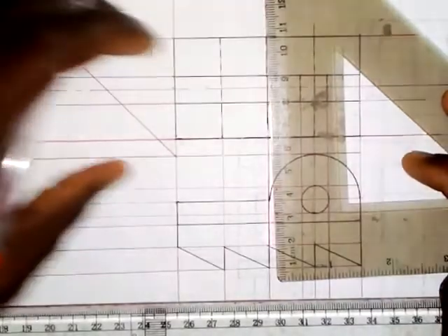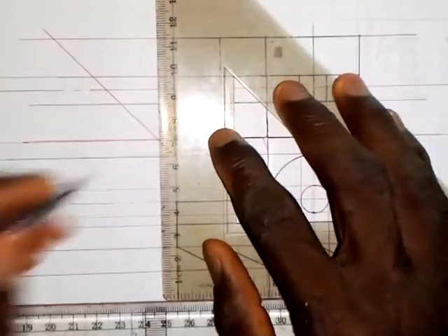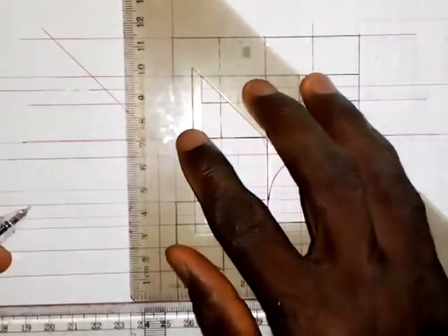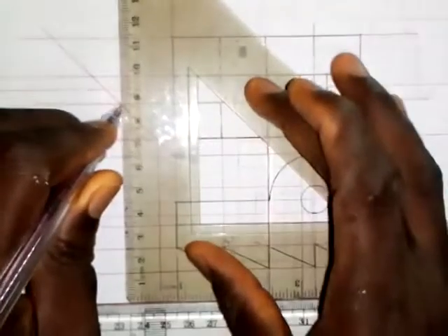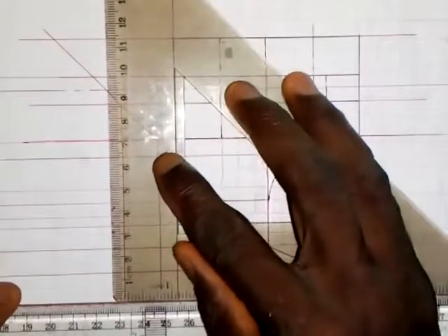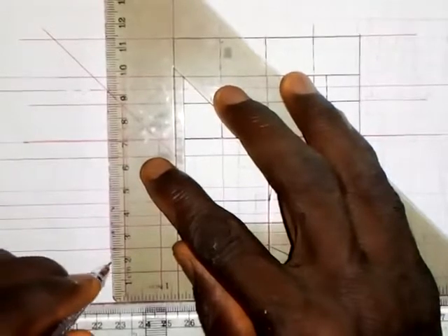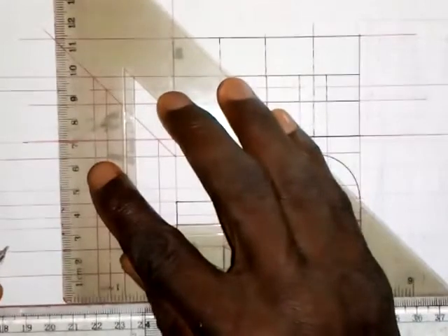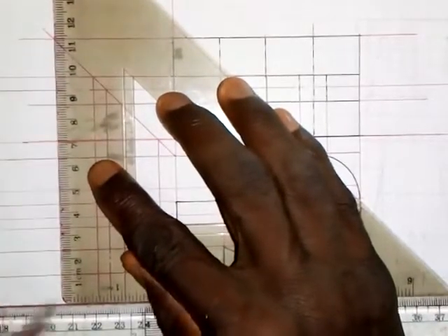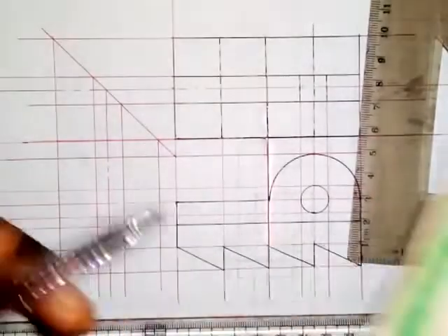So wherever this line touches the horizontal lines that will produce out of the plan, so we project it down. So here also we project this. Here, this is a center line, so I want to leave it as a center line. And then we also draw this, and then we draw this like this. Okay, so let's see how the end elevation will look.